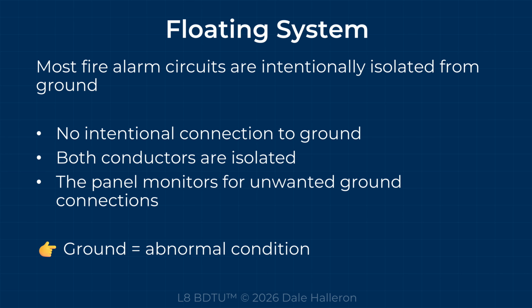A floating system. Most fire alarm circuits are intentionally isolated from ground. No intentional connection to ground. Both conductors are isolated. The panel monitors for unwanted ground connections. Ground is an abnormal condition.